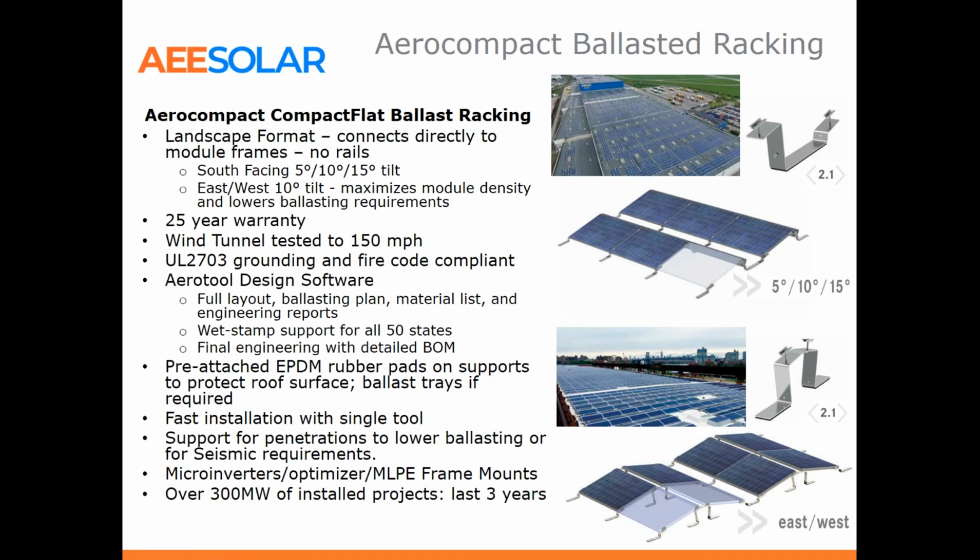One thing to note is that ballasted racking is in a landscape format, so that keeps the back end of the module from being really high up in the air and grabbing the wind. Some notations, though: if you're in high snow areas, being that the modules are grabbed on the edges of the frames, we do want to make sure that we're not risking the modules getting damaged from higher snow loads. There are alpine brackets that we can put in which support the panels in the middle of the feet if needed. So we want to make sure those are designed right, and we'll take care of that for you there.